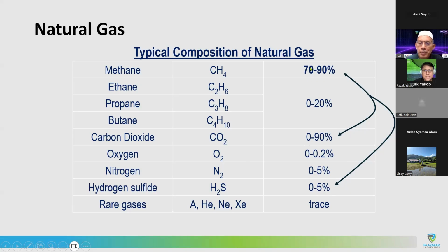In Malaysia, in Sabah and Sarawak, we have discovered gas, and most of our gas consists of about 20% CO2. So you have 20% CO2, and your methane is left at only about 80%. In the Natuna Island, we have CO2 up to 60%. So if CO2 is 60%, your methane is only about 40% of that volume. So say you have 100 barrels of gas. If the CO2 is 60%, then you have 60 equivalent barrels of carbon dioxide, and the other 40 barrels is methane.